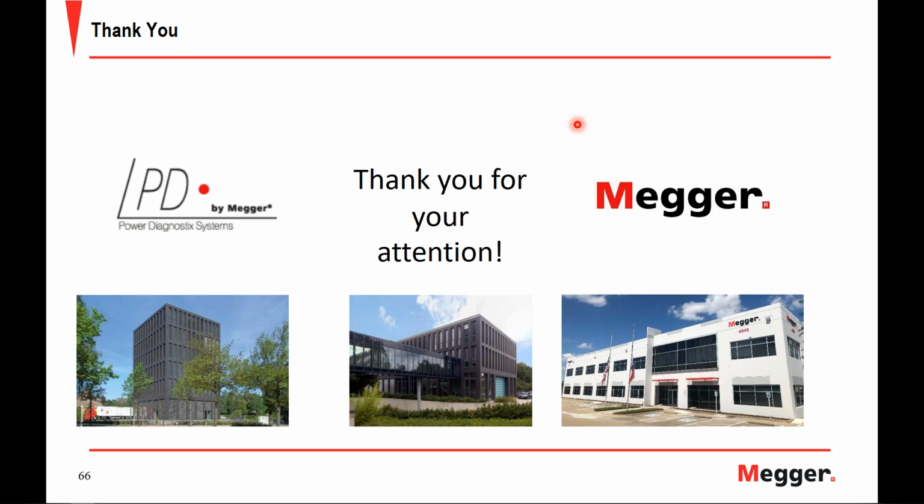All right, thank you. Charles, can we measure motor tan delta, capacitance, and PD at the same time with the ICMflex? Yes, it is capable of that, and it does have the multi or simultaneous update as well. The ICMflex is capable of performing your tan delta capacitance measurement as well as your partial discharge measurement. And that's one of the advantages of the ICMflex for testing rotating machines: you're able to get all three of those key measurements. So it is capable of performing those measurements at the same time for your motor testing.